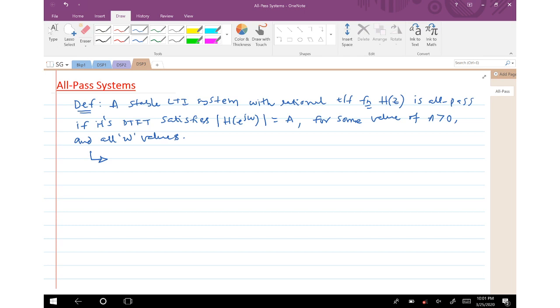The reason being, this keeps the gain of the magnitude of the frequencies constant across all frequencies, and at each frequency it could be designed in such a way that you get frequencies closer to the desired frequency. So they affect only the phase of the signal and not the magnitude of the frequency spectrum.